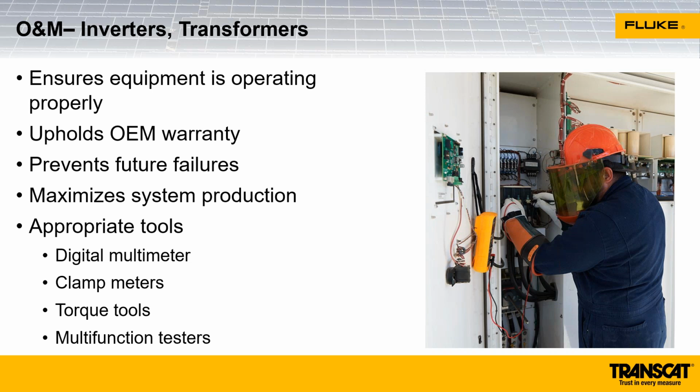We also need to know that if we're working on transformers that are on the utility side of the inverter, that's most definitely a category 4 environment. So we need to make sure that we've got the appropriately rated test tools there.